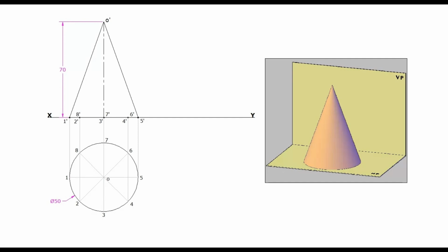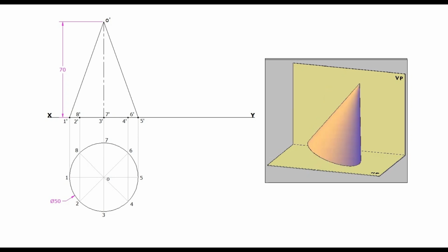There are no triangular faces or slant edges for a cone. So, the extreme end generators alone must be drawn dark. These are the projections of the cone, with the condition axis perpendicular to HP and parallel to VP. In the actual case, the cone is resting on the ground, with its generator perpendicular to HP. In the elevation which we have drawn now, the generators are inclined to HP. So the generator is to be tilted, to make it perpendicular to HP.